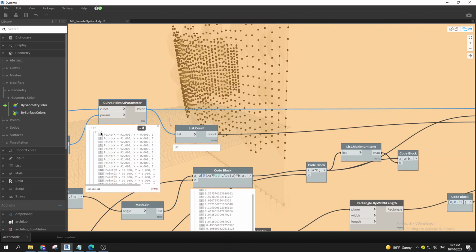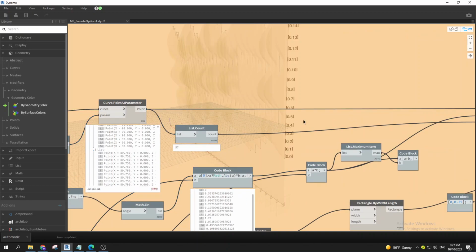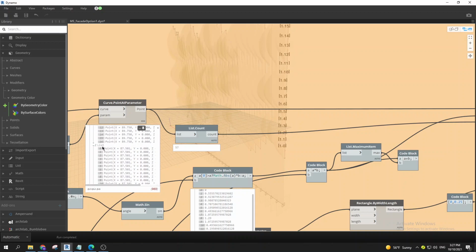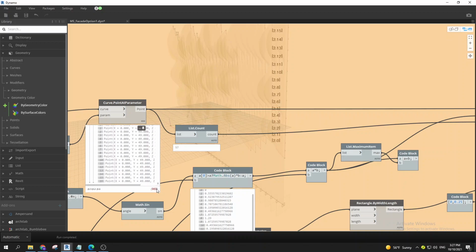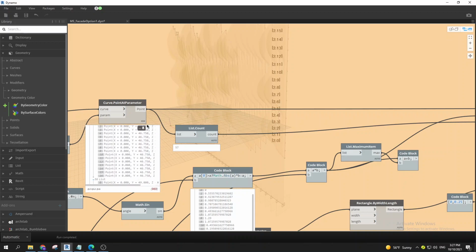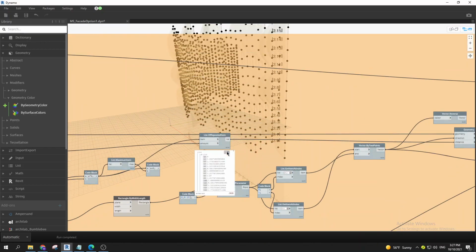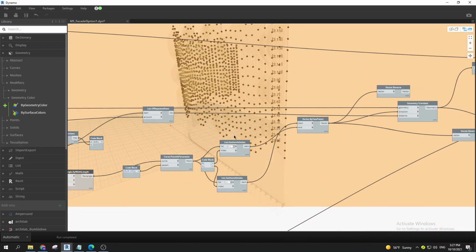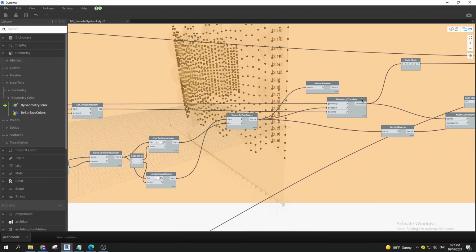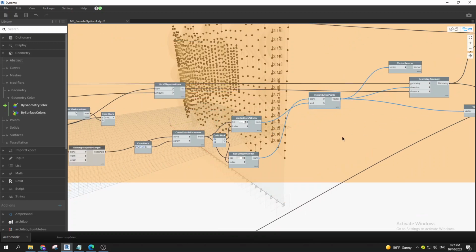So we get the count of this list, because now we only have it for one element, but here we can get the proper amount of items. So we calculate how many lists we have here, and we have 57, and then we can use list of repeated items, right? And there we go, and here we just move them by the vector that I've showed you previously.